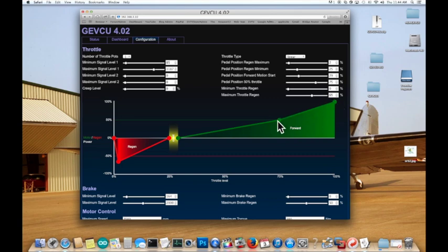Now, why would I want to do that? Well, from half of my torque to full torque, you're talking about putting the pedal to the metal, so I don't need very fine control here. I'm either stepping on it or I'm not. But on the first 50% of the torque, by stretching it out over 50% of my throttle throw, I get a much finer level of control, like in the parking lot and at slow speeds, because I've mapped this torque from 0 to 100% so that 50% of it happens in 3/4 of the throw of the pedal.